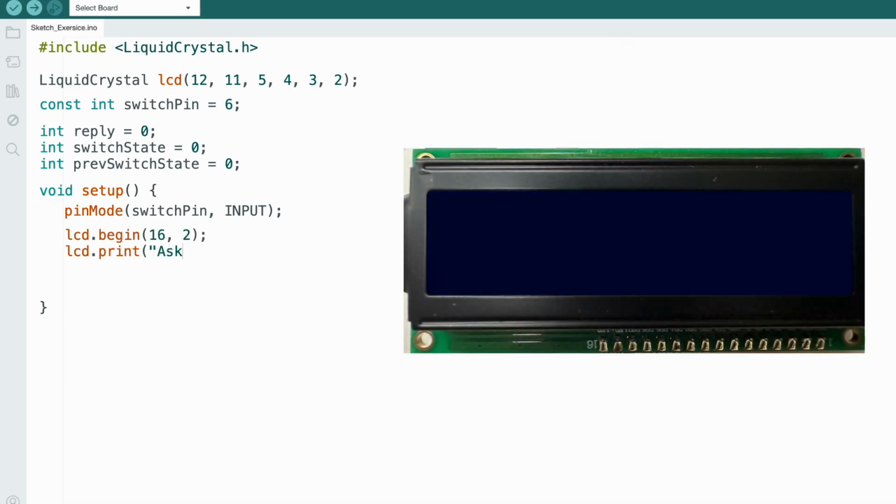Next, we are going to be looking at actually setting up the LCD itself, the piece of hardware. Here you can see that we have the LCD begin and the LCD print. What I want to do is focus initially on the LCD begin. You'll see these 2 numbers, 16 and 2, in the parameters to that method call. And what that represents is 16 columns and 2 rows.